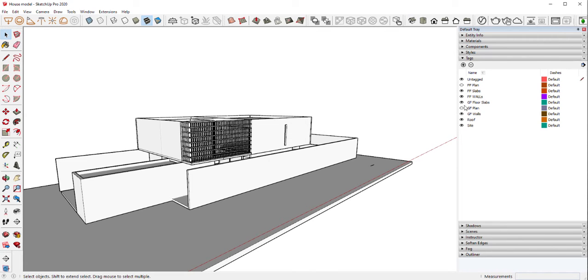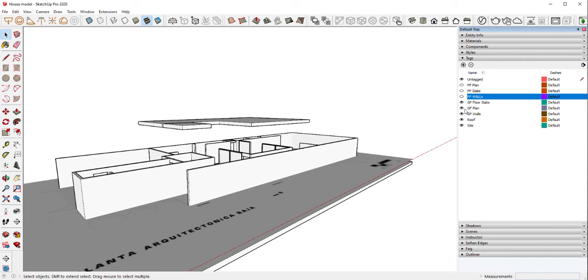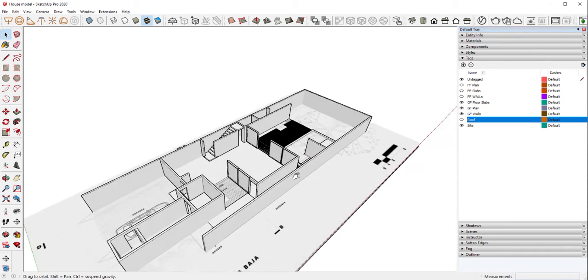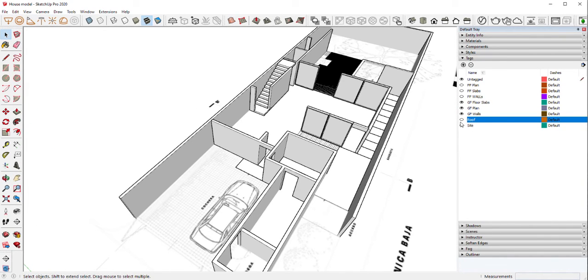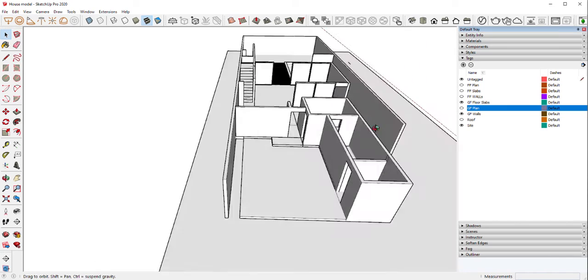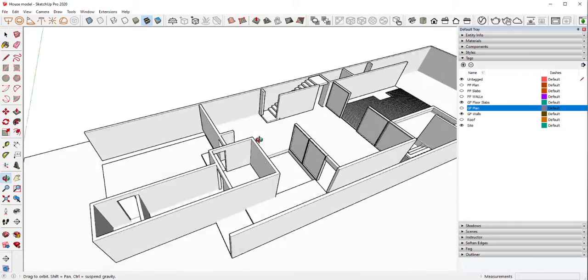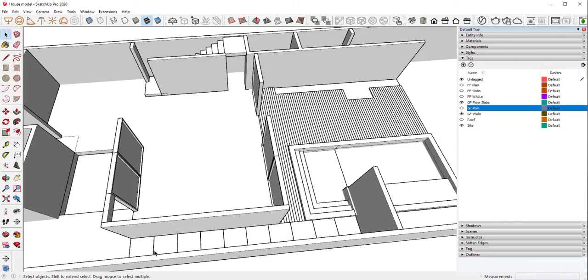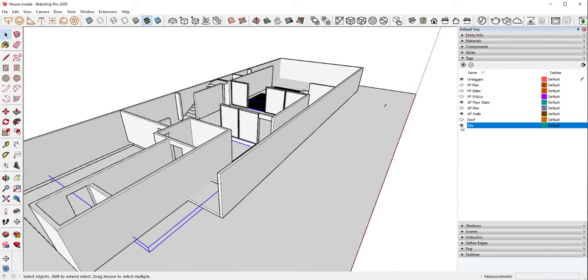So we have ground floor plan. This is what you will end up with. We can hide the floor plan after we are done with modeling the floor plan, and just by analyzing what you have in your image, you can create separate slabs. All of them are in the walls and slabs. I have side modeled a bit, but you don't need to do that.